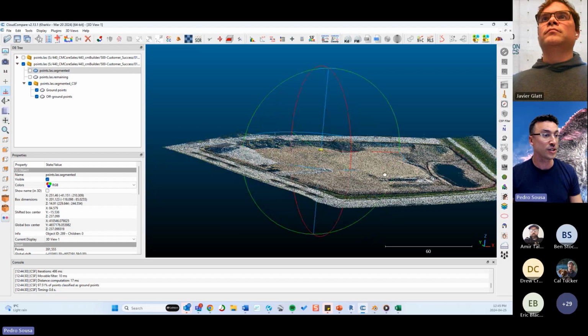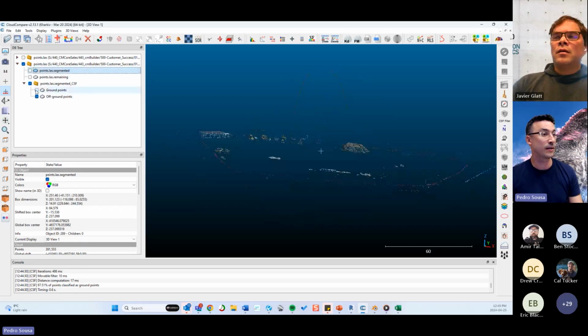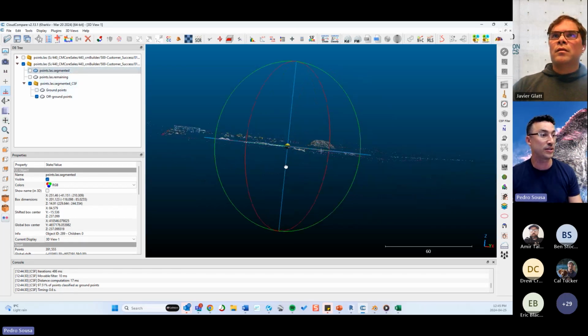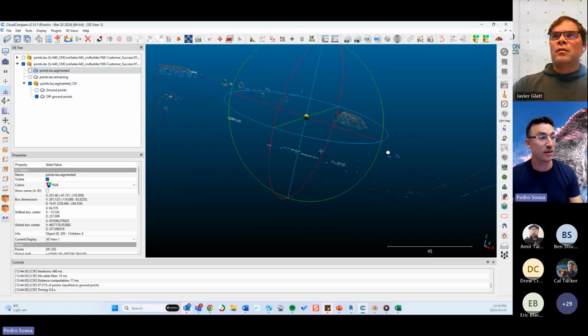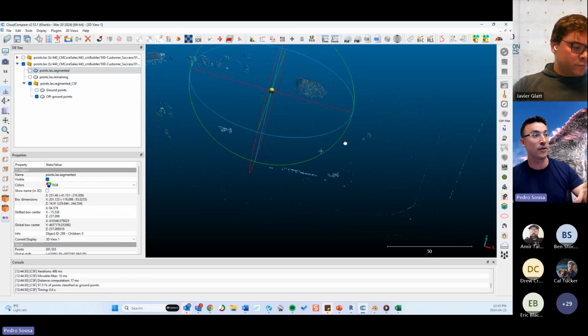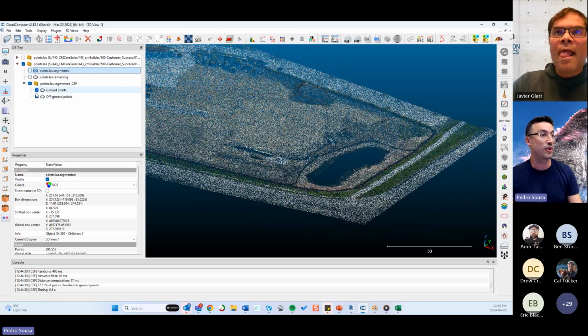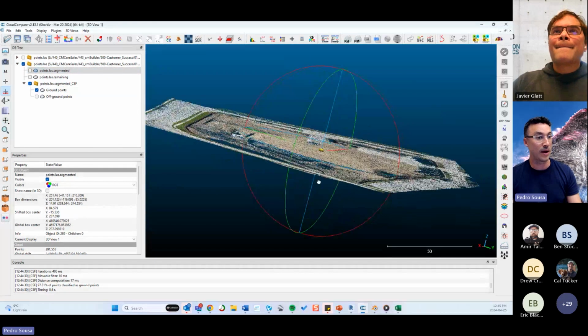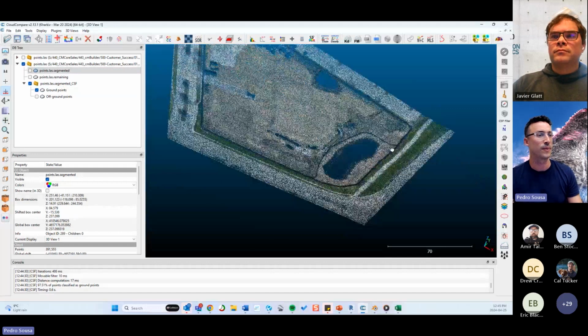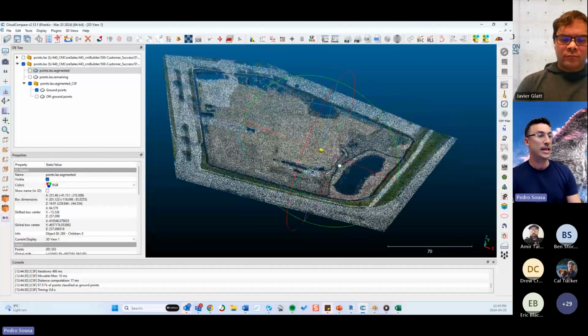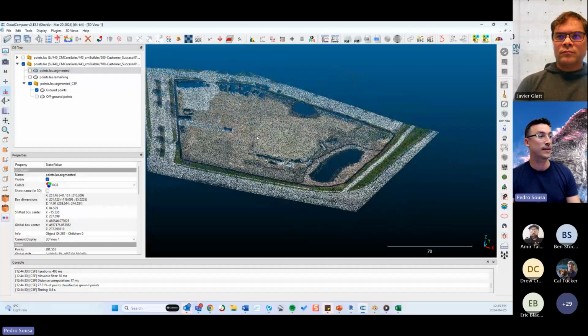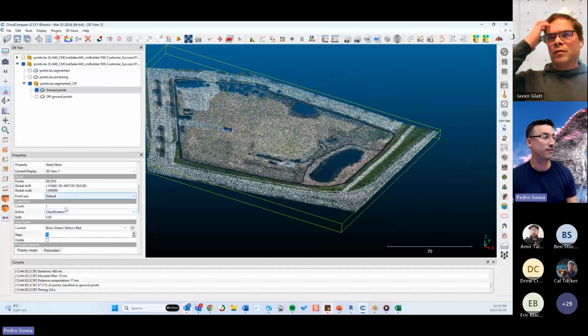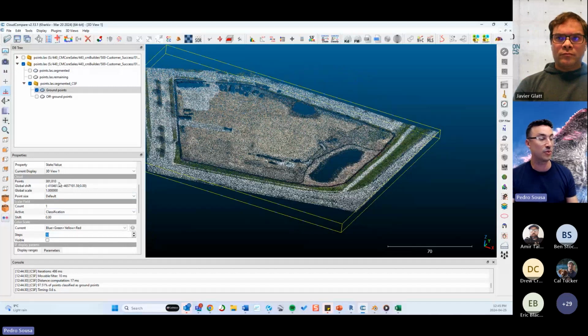Cool. So now I can choose over here, if I deactivate the ground points, you see, these are all the points that are represented over here that are not on the ground. And if I keep the ground points, these are the points that are on the ground. So it's quite smart. I really like this tool. Cool. And the next step now is for us to select this and see how many points we have left on this point cloud. My point cloud was exported as 500,000 points, but after what I did, I'm left with 380,000 points. That's still too much.